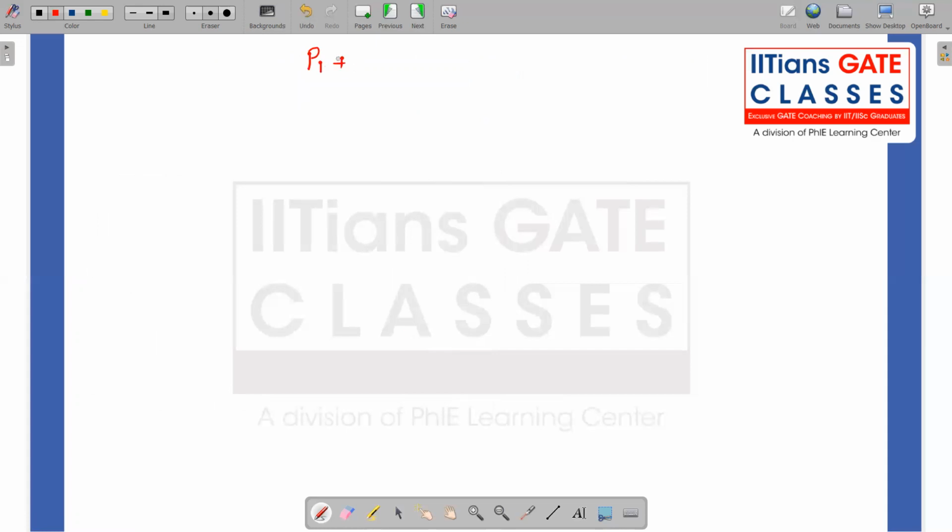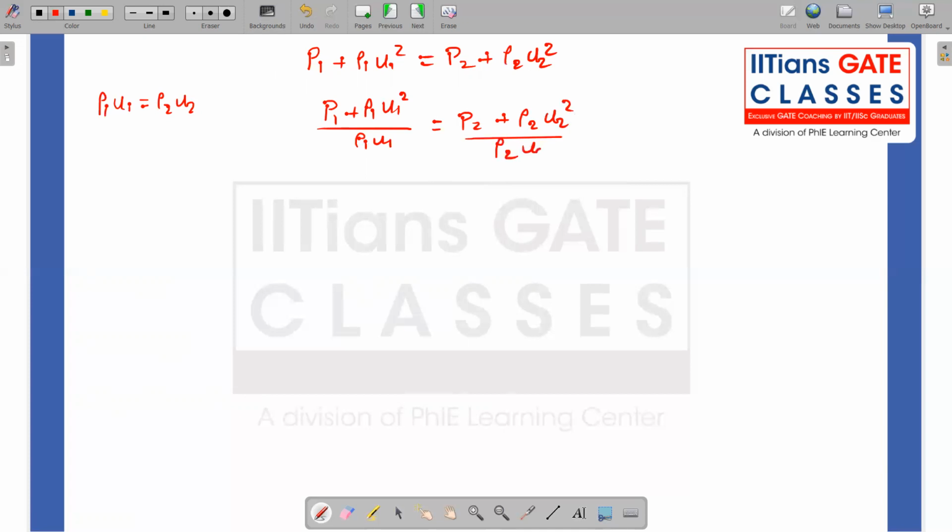So I had the momentum equation, that is P1 plus rho1 u1 square, which is also equal to P2 plus rho2 u2 square. And if I divide the whole equation by the continuity equation, that is rho1 u1 equal to rho2 u2, so that turns out P1 plus rho1 u1 square divided by rho1 u1 is equal to P2 plus rho2 u2 square divided by rho2 u2. So now what happens? P1 by rho1 u1 plus rho1 u1 square by rho1 u1, that only gives me u1, is equal to P2 by rho2 u2 plus u2.